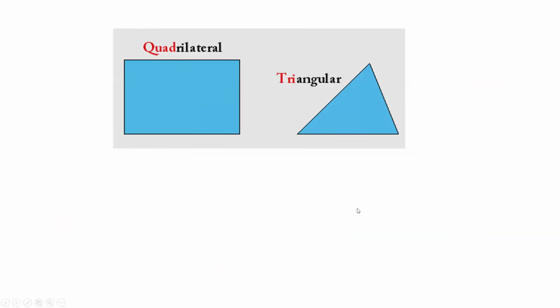Okay, so I'm trying to explain the different quality metrics. Because I said that the skewness is about the angle of the element, then we have the aspect ratio, that is the ratio of the two sides of our cell. And the third thing is the volume ratio change, that should be not more than 20%. So all these things combinedly will define the orthogonal quality. So what should be the range here? So orthogonal quality